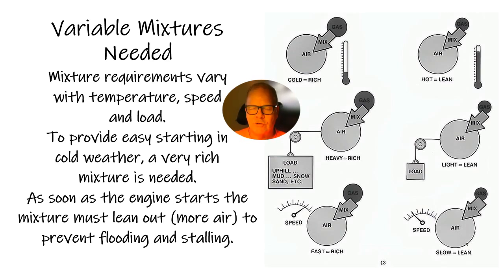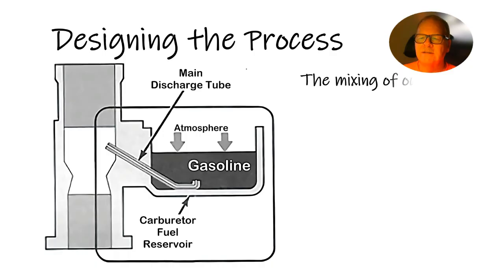I used to stretch the spark at the coil wire to get one to start up, and then I let that spark stay stretched at the coil wire after it started until it burned all that junk off them plugs, and then I'd put the coil wire back in. Now sometimes I dodged a bullet and didn't have to pull the plugs and clean them for that reason.